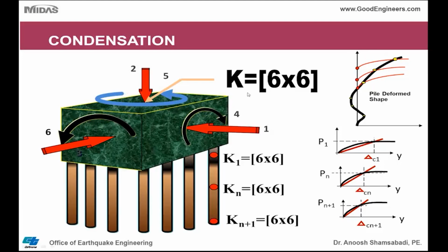You basically model the foundation, you push the foundation or the pile to come up with a deformed shape, and as a function of the deformed shape, you put a 6x6 matrix at every node. Because remember, this is an element which has six degrees of freedom at each node. The foundation springs are linearized and incorporated into the 6x6 matrix at the element, and then you condense all of this foundation, including all the 6x6 matrices, to a 6x6 matrix at the bottom of the column. That replaces your entire foundation with a 6x6 matrix, so you don't have to worry about the foundation.